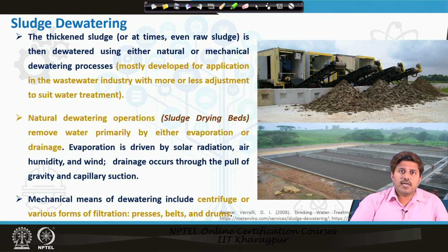Okay. So mechanical thickeners, at which stage are we using them? If we are feeding a very raw sludge, it will just thicken to a certain percentage. If we are using a more thickened sludge, or recycle that again to this thickening process, particularly the mechanical thickening process, then we are going to get a more elevated solid concentration. So they can be considered as an option for dewatering as well.